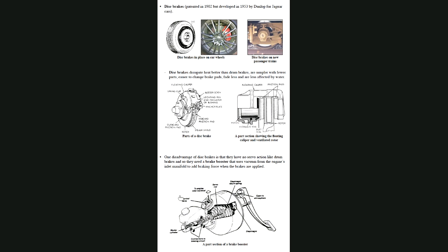So when you put your foot on the brake, it opens up this valve to the low pressure area of your inlet manifold, and you've got a big diaphragm, which is spring loaded. And as you suck the air out of here, it pulls the diaphragm along, and your diaphragm is connected to the shaft in your master cylinder. So the more you put your foot on the brake, the more this valve opens and the more assistance you get with your brakes. And this is called a brake booster. And I'll show you what a brake booster looks like.